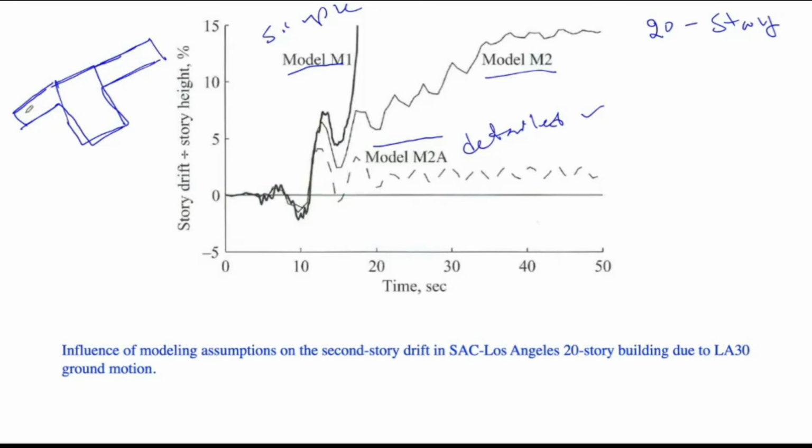Okay, and there is some interesting work going on with respect to the rectangular beam as well as the T-beam. And using a T-beam should give you a more accurate answer in comparison to the rectangular beam, if the beam and slab are casted both monolithically. But if you look at the fact, this is the scenario that we always assume in the design as well as in the assessment. So you have to also pay attention to these cases, which are quite common in our area.